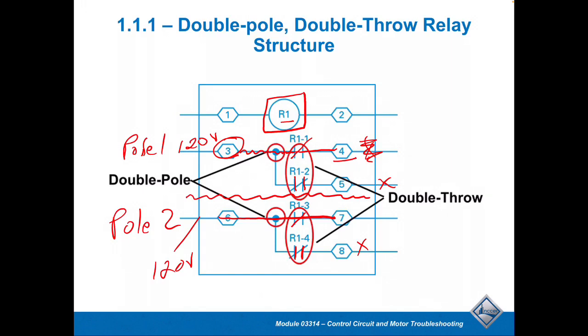It could be voltages that are being backfed from other devices. It could be another motor lead, as an example. So it's just something to be aware of. Even though the circuit might be open, it still potentially could have some power on it.